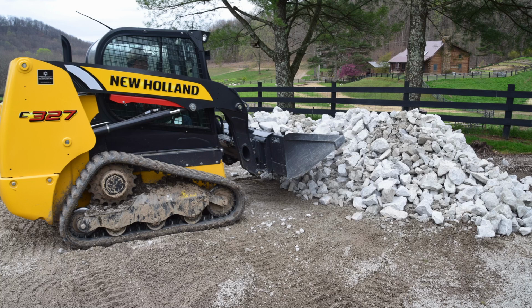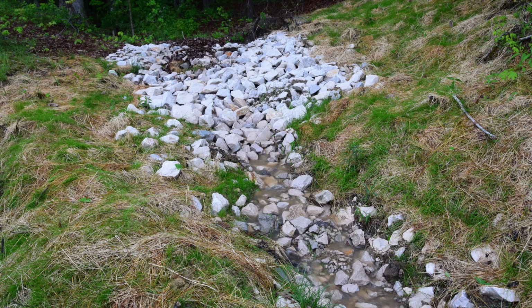Here John is using a skid steer to move the rock to where we were controlling the head cut behind the barn. John used the excavator bucket to place the rocks in the trench and to pound them into the ground. He sloped the vertical face of the head cut and formed a ramp for water to flow over the steep ground. He also placed soil over the ends of the rock-filled trench to form stream banks.